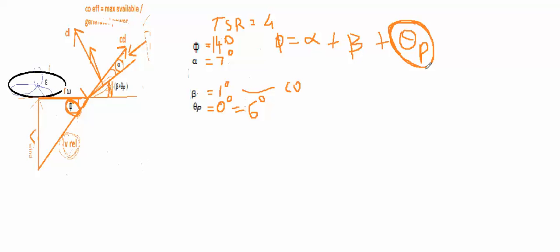Now the question is, what about the other elements? This was a single element, so now we know that if we pitch the blade at 6 degrees, this element would experience the best possible lift to drag ratio. But what about the other elements? There are so many elements along the length of the blade. Will they be experiencing the same lift coefficient and drag coefficient? No, they won't be. For that, just make a spreadsheet and plot all the elements.